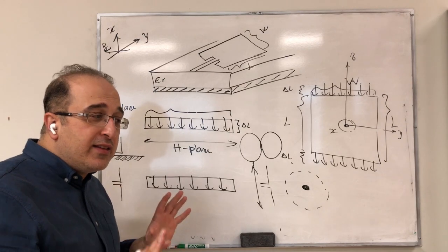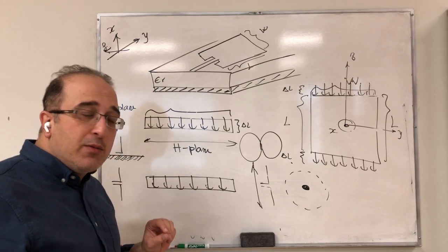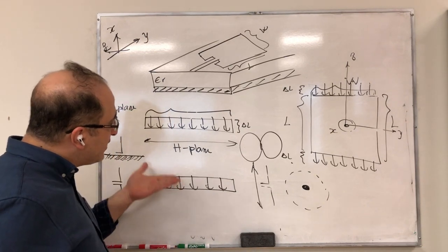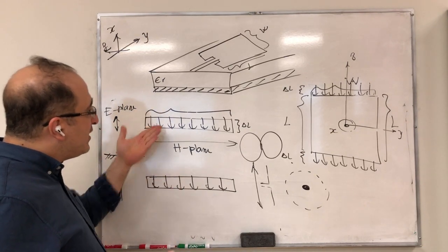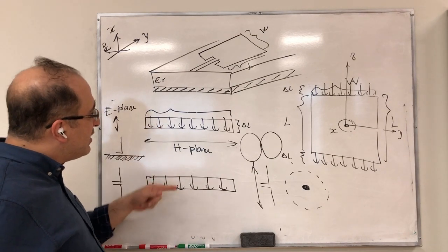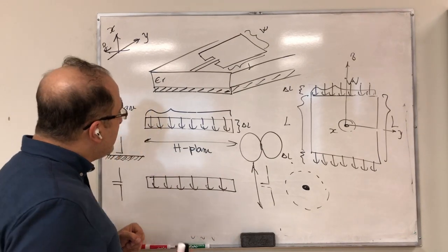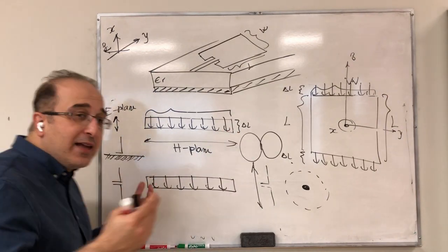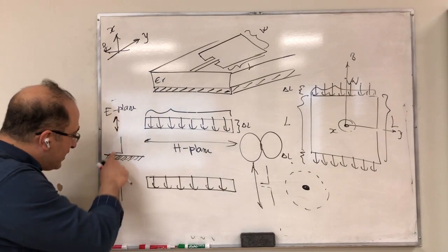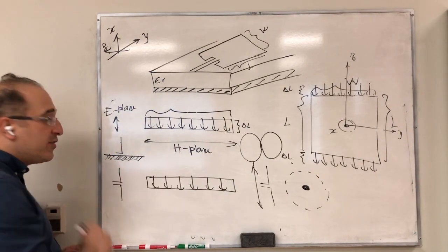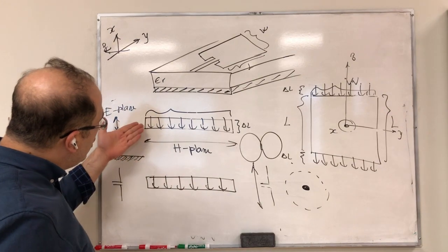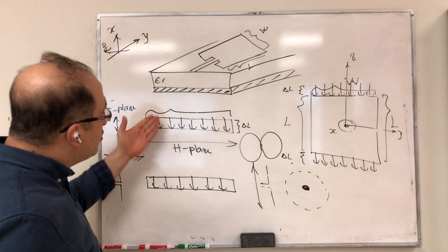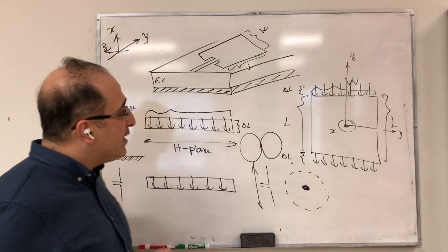And you remember the directivity when it comes to arrays is not that easy. You need to calculate it, but at least we know that roughly speaking, you can get twice the directivity because you have two elements. So if you know the directivity of this element, and you have a ground plane that enhances the directivity, for example in the case of monopole and dipole it increases by 3 dB, then you can potentially double the directivity, or add 3 dB, because you have two elements here.